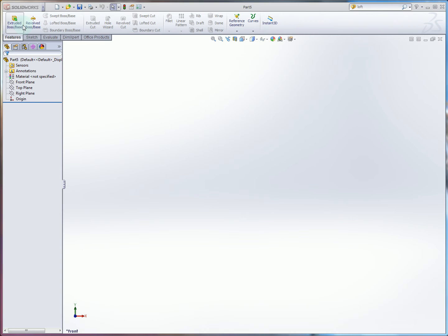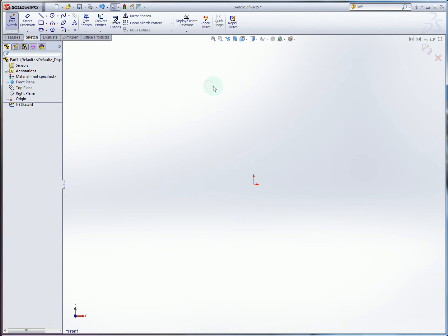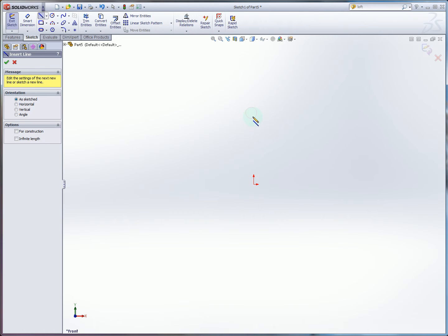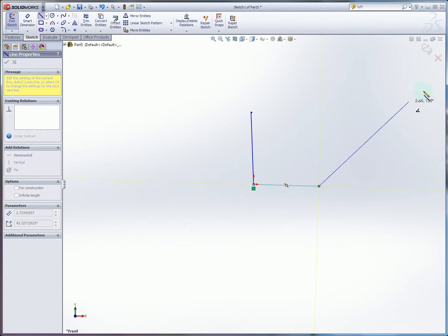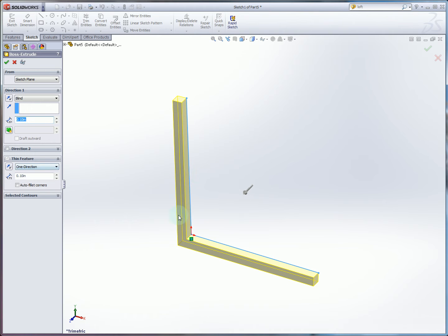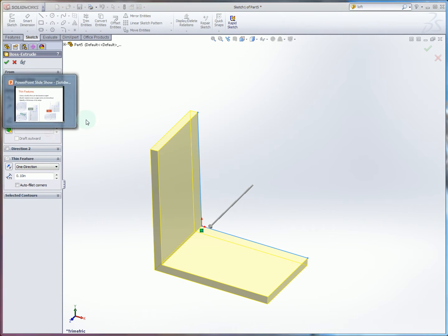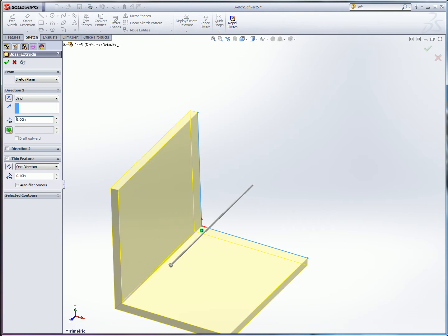To see what this looks like in SOLIDWORKS, we're just going to go to create extruded boss/base. And I want to show you what happens if we start from the feature creation first. So not creating a sketch first, but a feature. Let's say I want to create an L-shaped section. So I'm not going to worry particularly that it's not perpendicular. We can see that because I left the sketch open, it assumes that I want to do thin feature. So then when I extrude, we'll make that 2 inches.